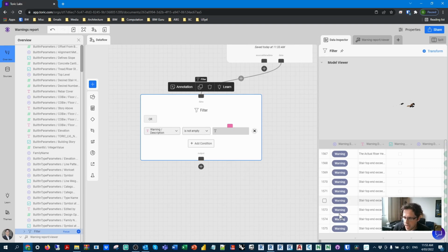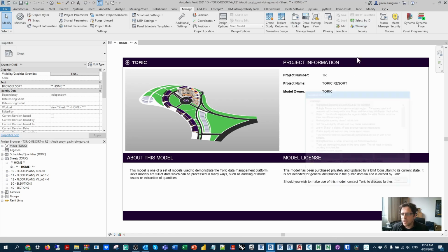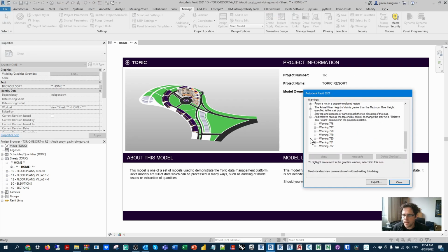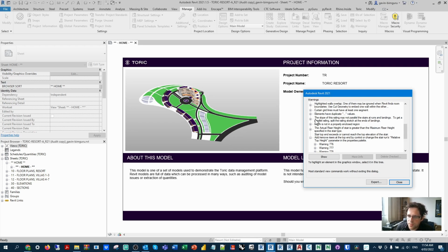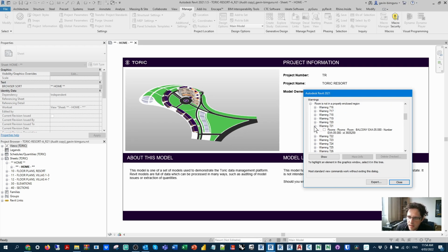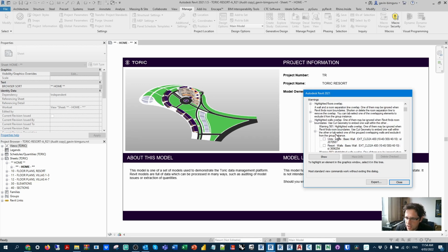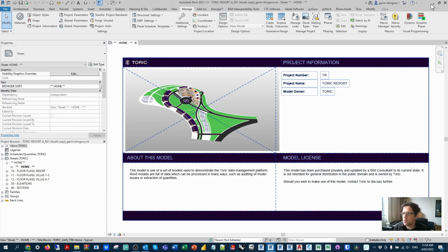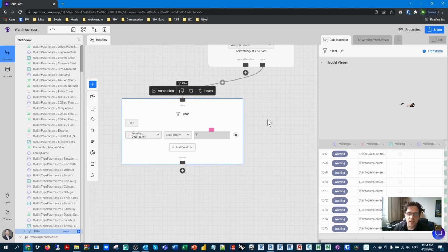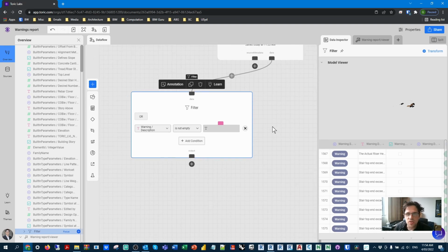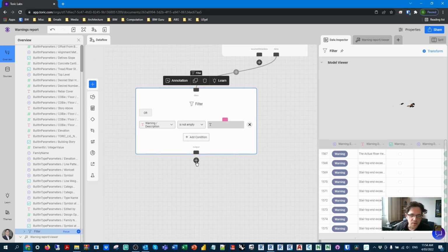So we can see currently we have about 1,500 warnings. However, in Revit, the warning object count is actually closer to about half of that, 782. Sometimes warnings relate to one object, sometimes they relate to many, and sometimes they relate to, in this case, pairs of objects. So I found it's just a rule of thumb. It's up to you whether you want to even show the current warning count. Up to you, of course. But in this case, I found that's one way you can at least determine a nominal number of likely warnings to exist in the model.